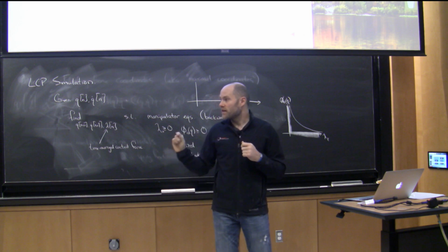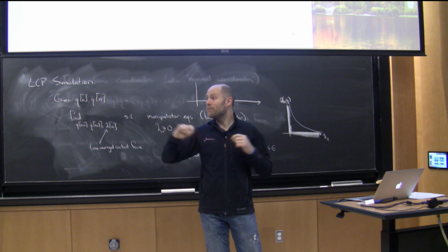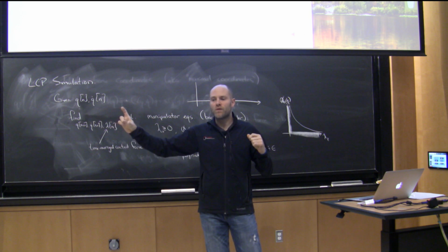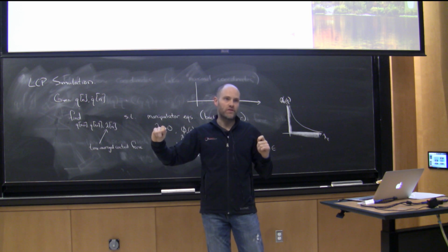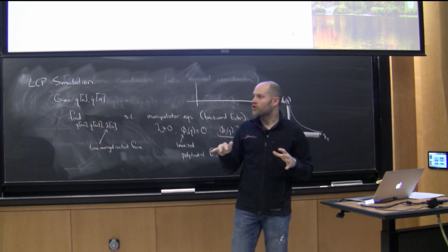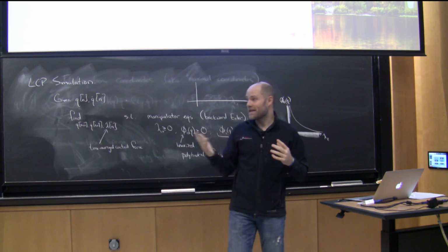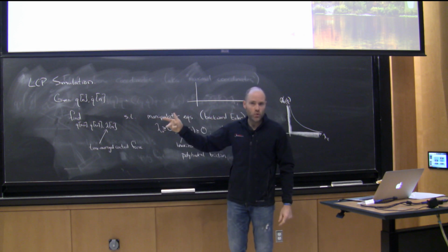And the reason that we had to do that was because when you went to stabilize the solutions that were coming out of this, they were not stabilizable because of numerical integration accuracy errors. And so it wasn't until we got a higher order accuracy that we got high enough quality solutions to stabilize. You can do LQR in the constrained coordinates.